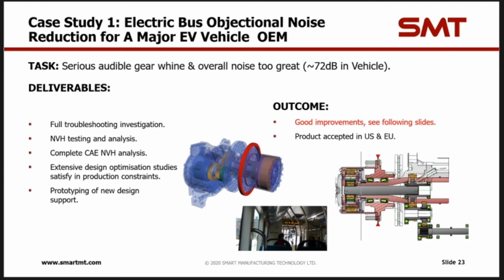The challenges in this project were that the layout meant the support of the first stage gears was not optimal, so misalignments were compromised, as well as the support of the motor shaft. So they had problems with gear whine associated with the first stage and motor.